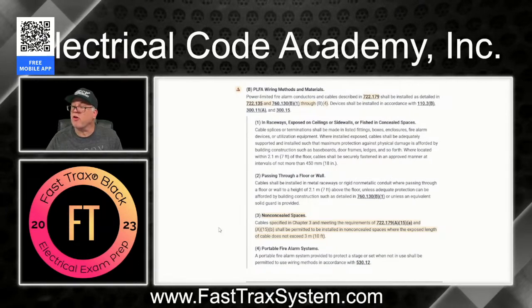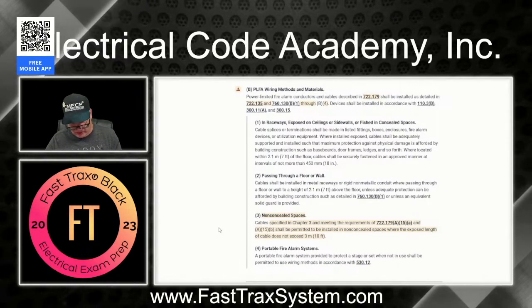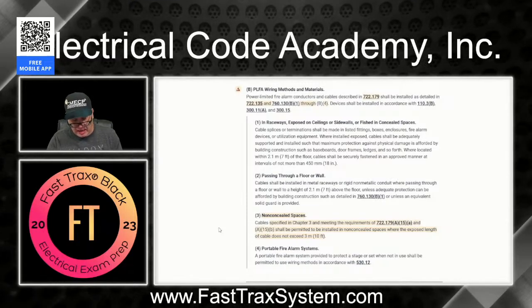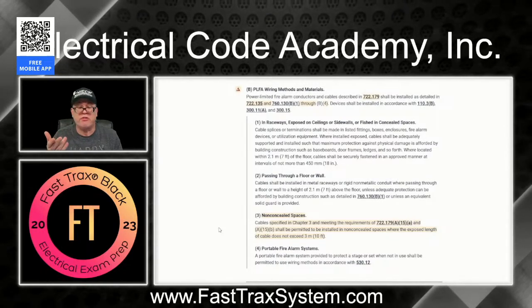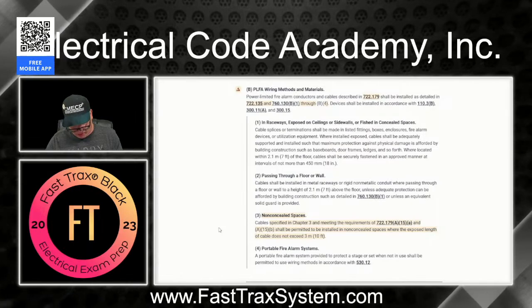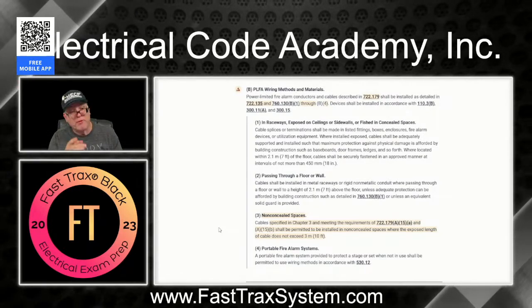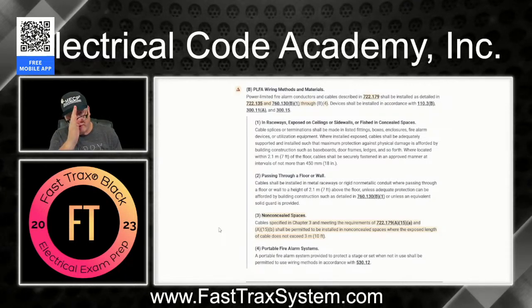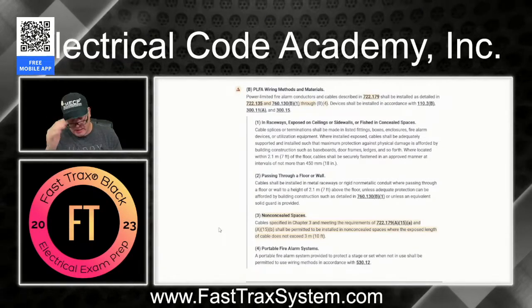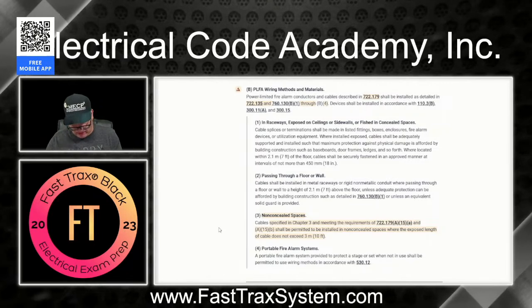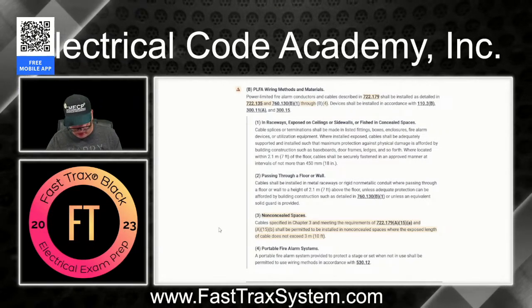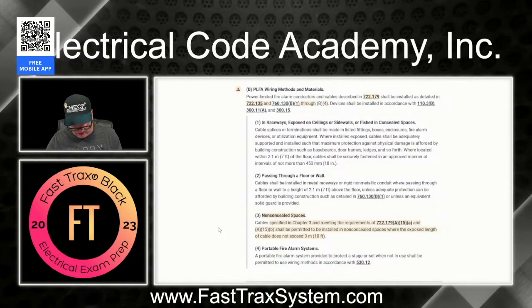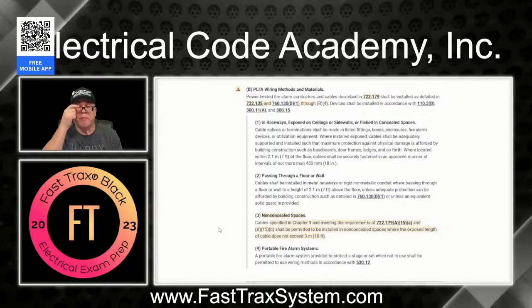Power limited, and I guess our question was for power limited. You go down, you'll see power limited, not non-power limited, power limited. That was our question. And that is part 3. Now, under part 3, if you're following along in your code books, folks, you see where the references are indented. That means they're germane to the power limited. And you go down and you'll see conductors size, 760.142, a great place to start.